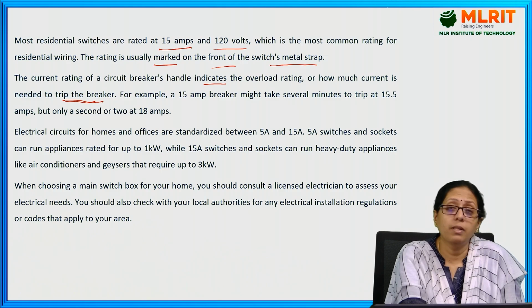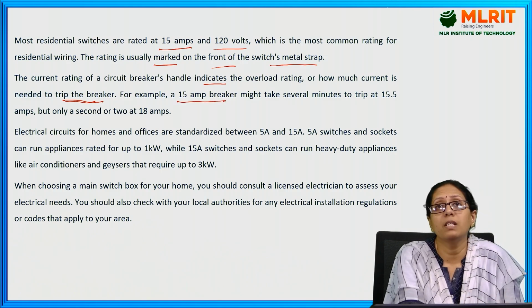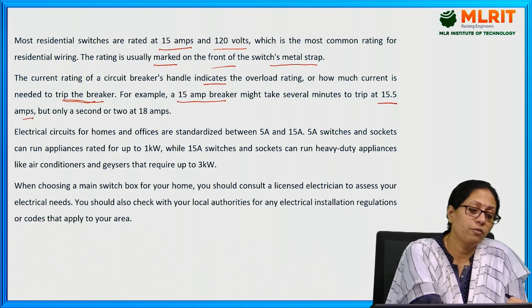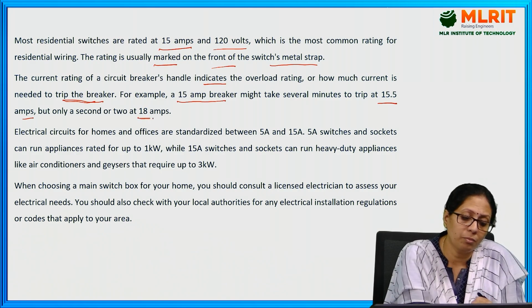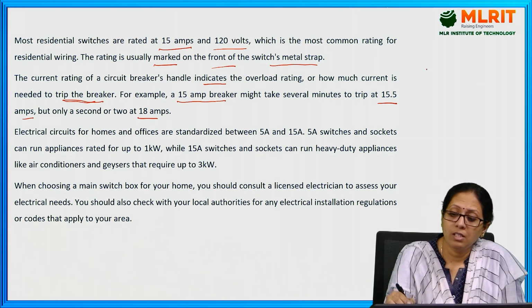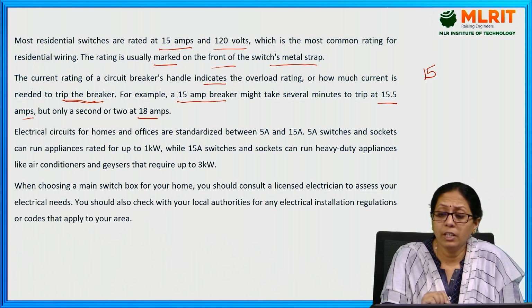For example, a 15 ampere breaker might take several minutes to trip at 15.5 amperes, but it will take only 1 or 2 seconds to trip at 18 amperes, because the capacity of that particular circuit breaker is 15 amperes.